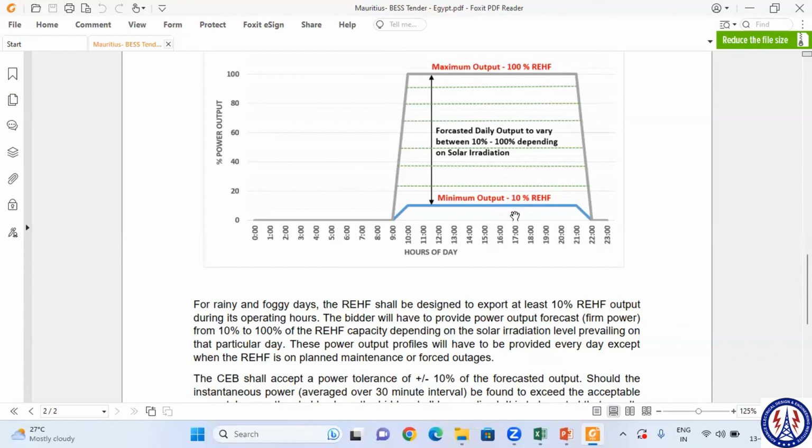Because if you see, to manage your entire system, if I'm considering 40 megawatt as a load, then for operating 40 megawatt constant for a 5 hour duration, what would be the energy? 40 into 5, correct? 40 multiplied by 5, that would be 200 megawatt hour. Am I right, Shahrukh?